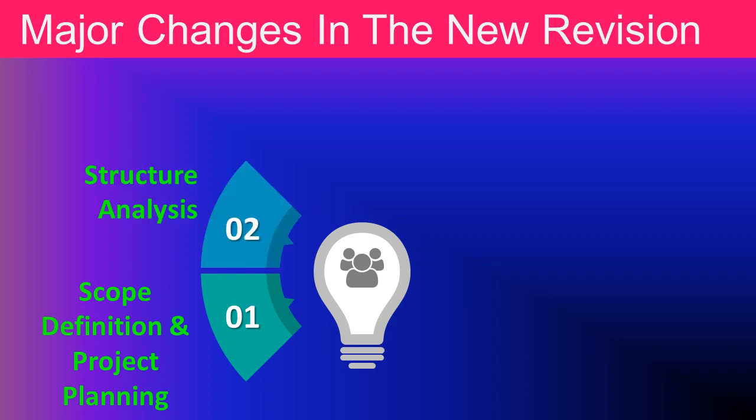The second step is structural analysis. Its purpose is to identify and break down the manufacturing system into 3 elements: process item, process steps, and process work element. Process item means the end result of all the successfully completed process steps. Process steps means the manufacturing operation under consideration. And process work elements, in this you identify potential causes with respect to man, machine, material, method, measurement, and work environment that could impact the process step.